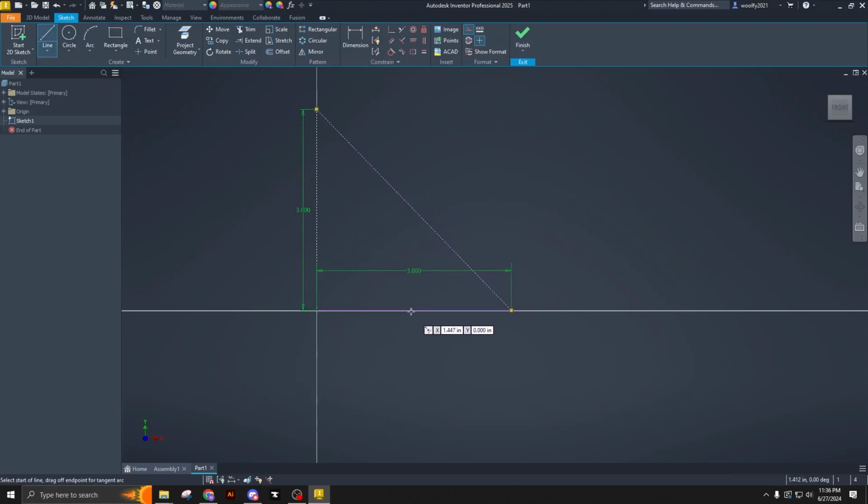The other thing I decided is, from this hole in the middle, I need my gear to rotate on a hole that is 1.125 or 1.25 vertically from that hole. So this just gives me the basic layout of where I need my locations for this custom part. I'm then going to turn off my construction line and select this green dot. That's where you have either a center point or a connection of 2 points, the end of a line, so they can be super useful.